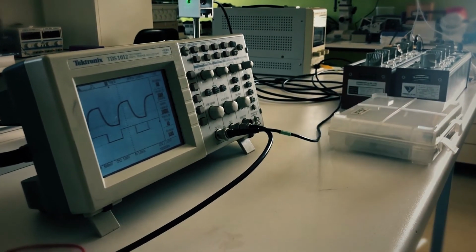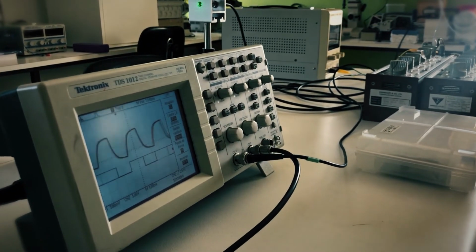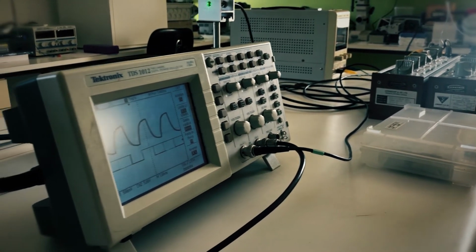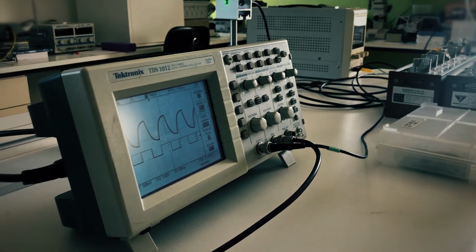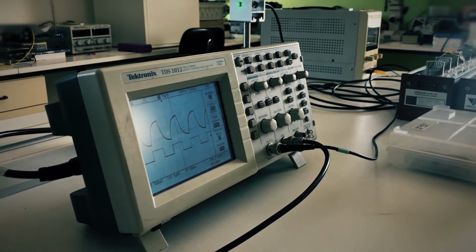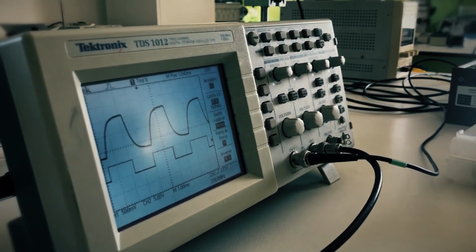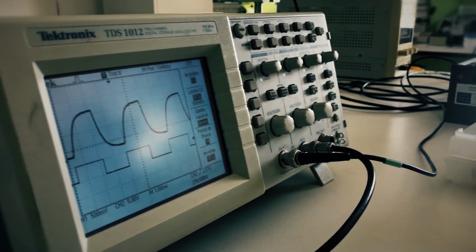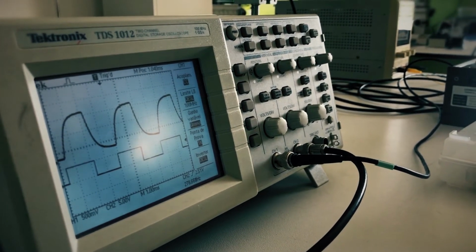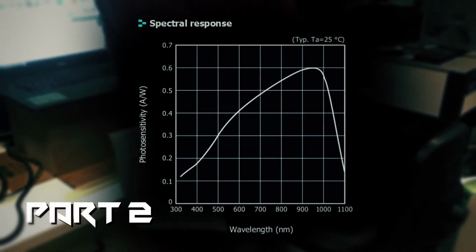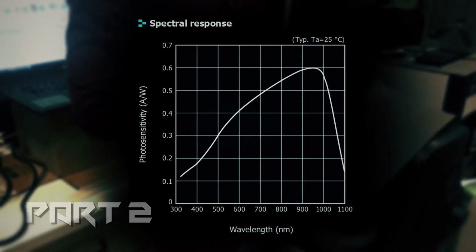This creates the same problem as increasing the internal resistance of the photo device, meaning that if we increase the light frequency, the photodiode will be unable to fully discharge and its response will be cut off. Contrarily to what we've seen before, increasing the reverse bias modulus won't solve this issue, since we're just simulating the intrinsic area getting thinner.